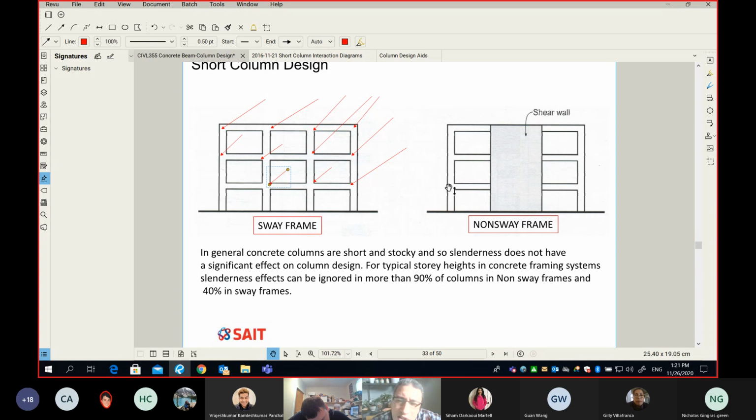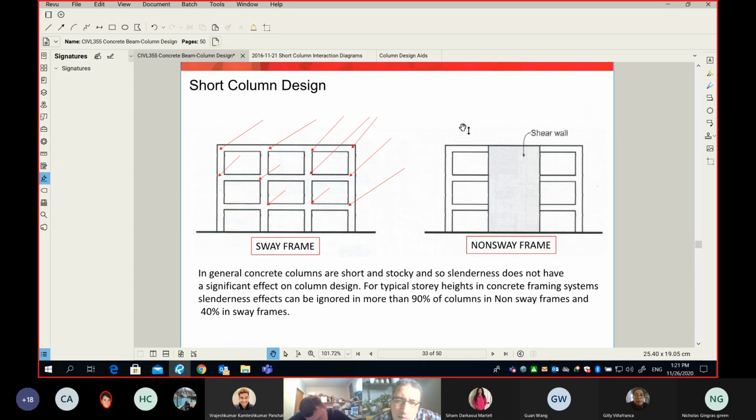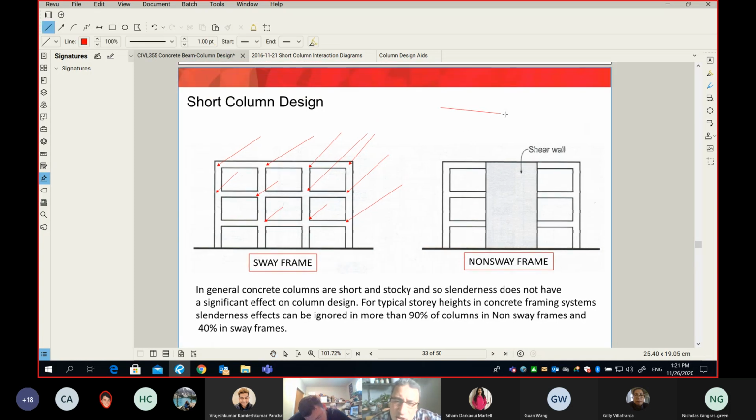How about the one on the right here? It simply does this. This is your beam, and your column is here, and we don't have to carry any moment. We simply assume that this point here is a hinge. It means if the beam wants to rotate, then the column says, okay, go ahead, do it, I'm not going to follow you.